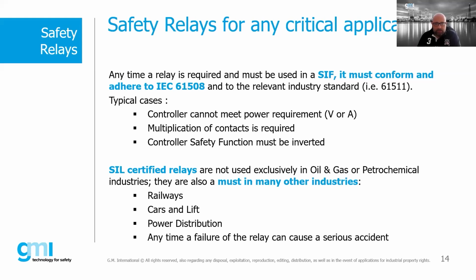Typically, a safety relay is used in all those applications where the controller, which is usually a digital output card of a PLC, is unable to activate a field device due to its limited potential in relation to the voltage and the currents involved. In other cases, for simultaneously activating multiple loads, a set of multiple contacts is necessary.